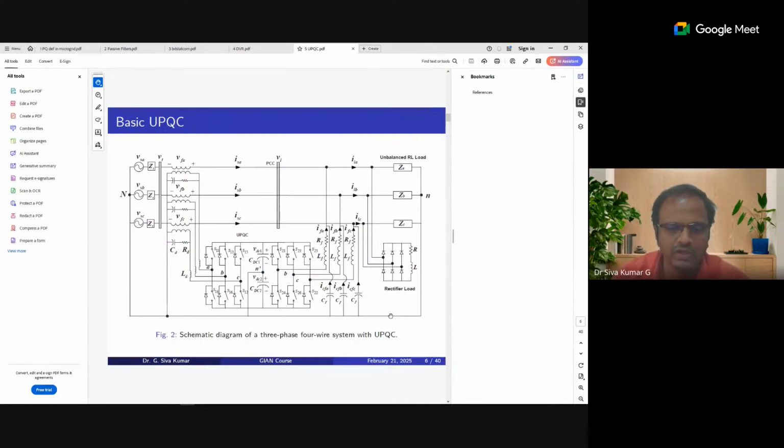You have voltage and frequency control loops. As we have seen, voltage and frequency control is the primary control, and in microgrid applications the hierarchy goes the same way. You are going to control the voltage and frequency all the time. It tries to maintain sinusoidal voltage and the nominal value also.